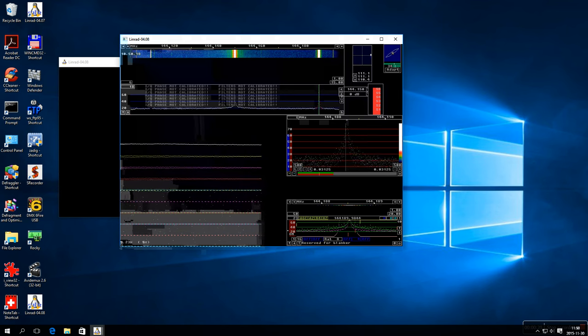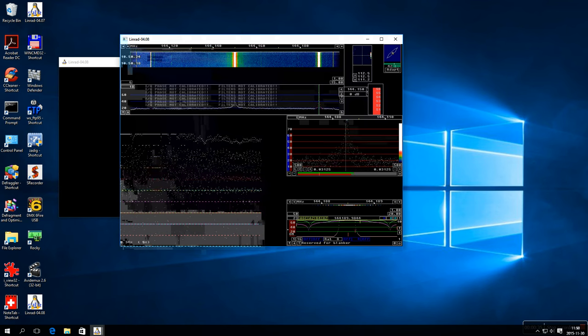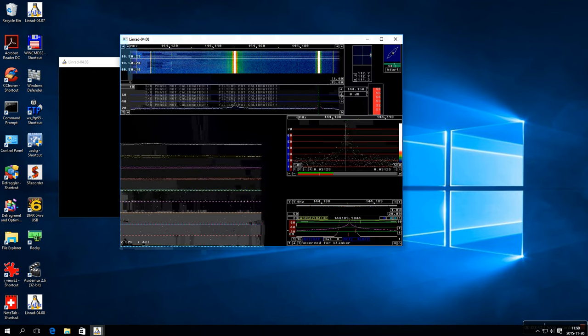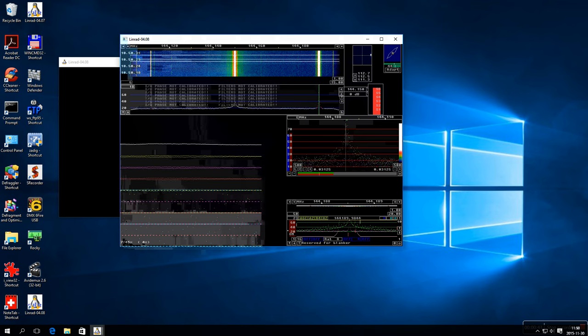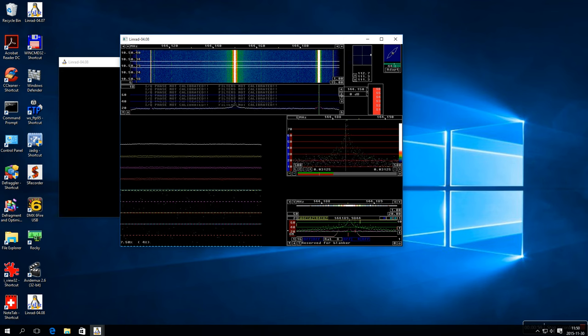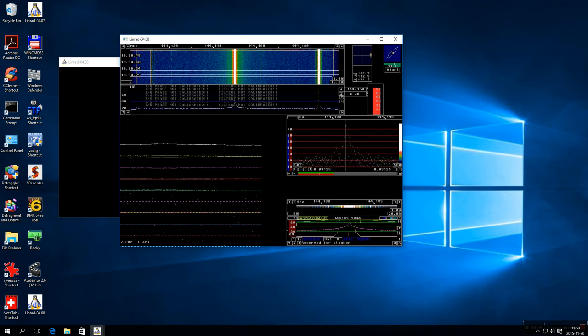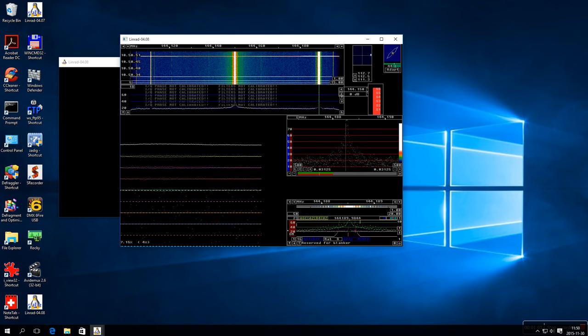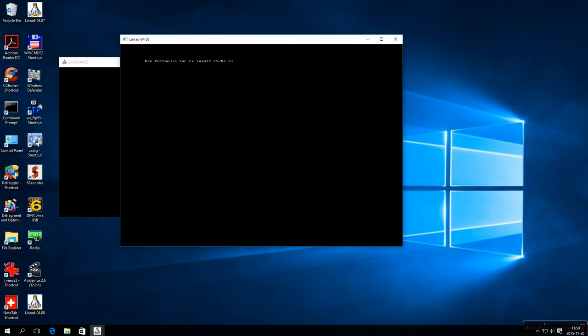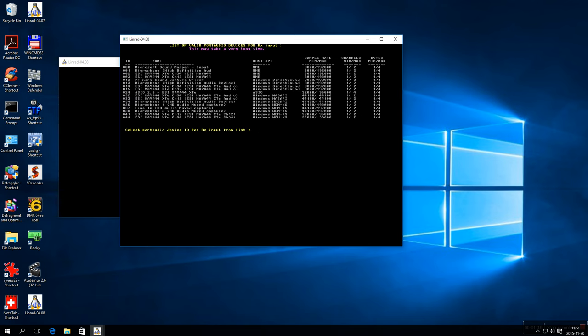So if you run this sound card with map 65, you will have a problem that the phase between the two polarization is undefined, and that means probably a loss of up to 3 decibels. The glitches can be because I have not allowed any latency. Remember, I put 1. But there are other options here. So X, and I go for U and A, and use port audio for input.